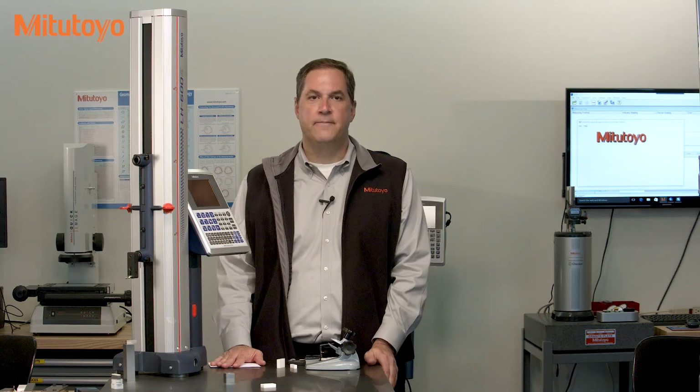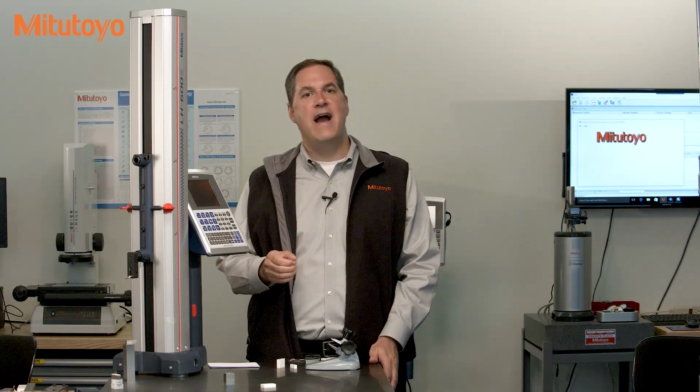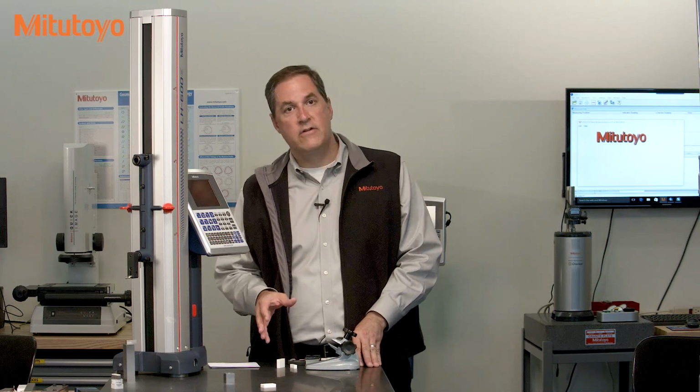Now, I'm not going to attempt to turn this episode into a lesson on uncertainty. We don't have the time for that. However, I can demonstrate a TUR calculation. For the interested viewer, you can find an example uncertainty evaluation for a micrometer calibration using grade 0 gauge blocks in the American National Standard on Micrometers, ASME B89.1.13. The final analysis in that uncertainty was 10 millionths of an inch. Since that seems like a reasonable, achievable uncertainty, let's use that to calculate the TUR.